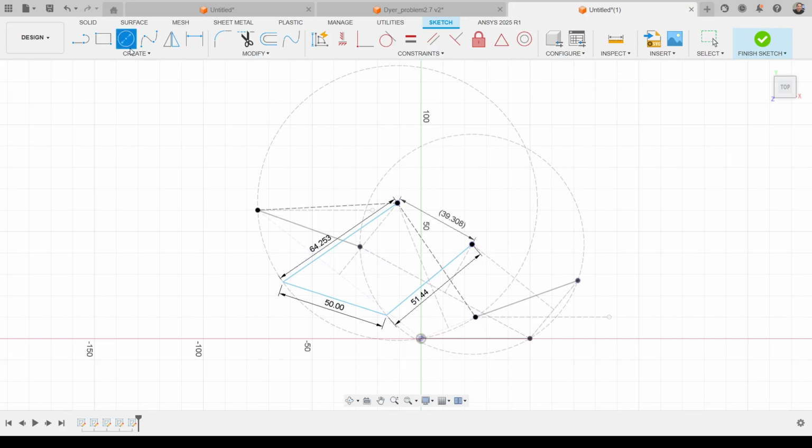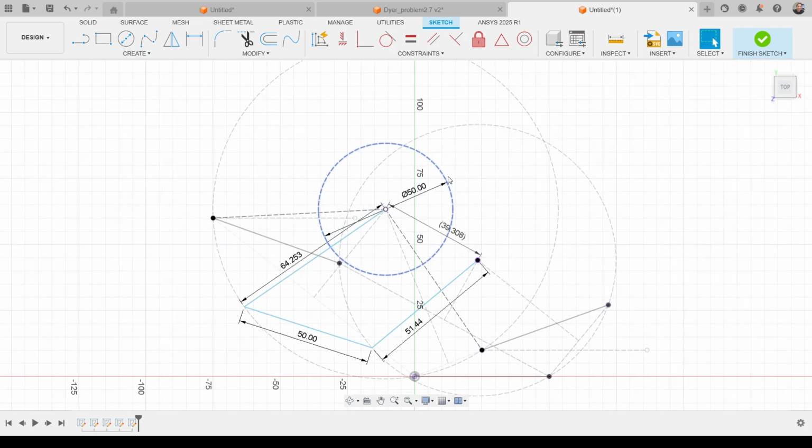So the next important decision is to decide where exactly in the link number 2 I will connect the diode. And for that I am using very arbitrarily, but we have taken a lot of arbitrary decisions, or engineering decisions, let's say. I will decide to have the diode connected 25 millimeters from the origin of link 2.